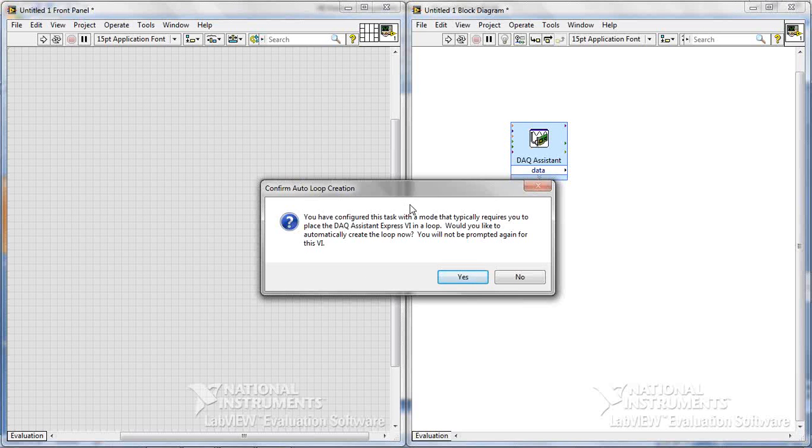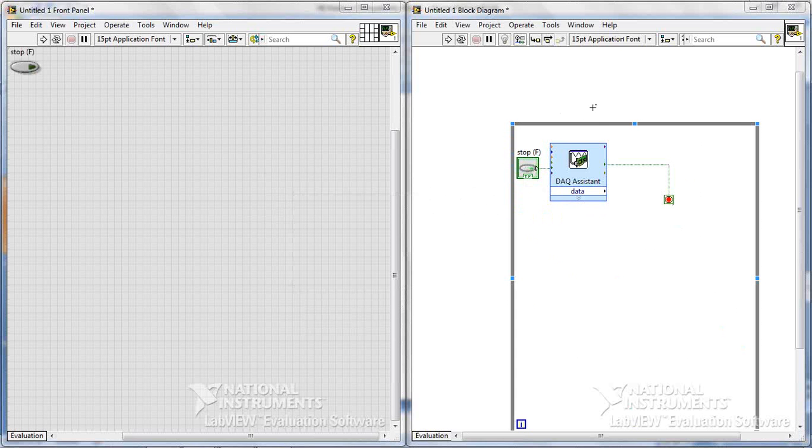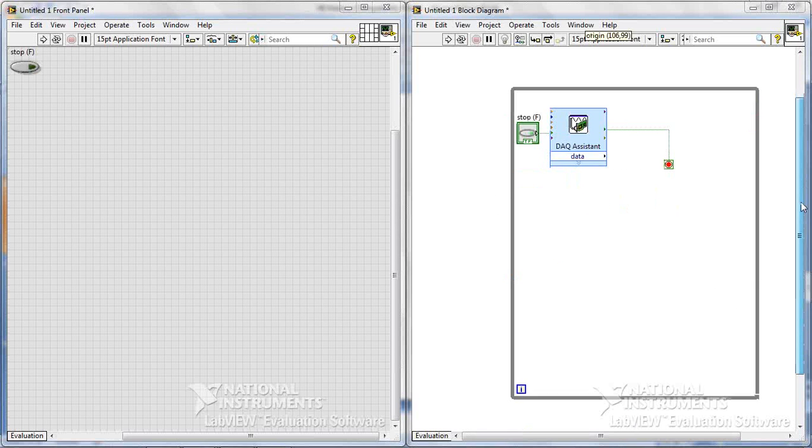So this time, since I've given it as a while loop, it prompts me asking whether you want to confirm this, whether you want your VI to run continuously. Then I'll just give S. The moment I'm giving S, my VI will just get into my while loop. So what will happen here is that I've done my VI, everything is ready.